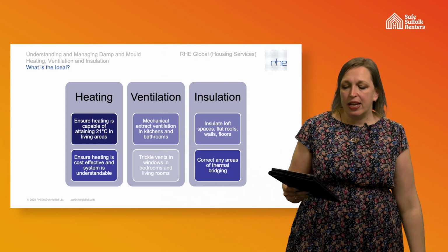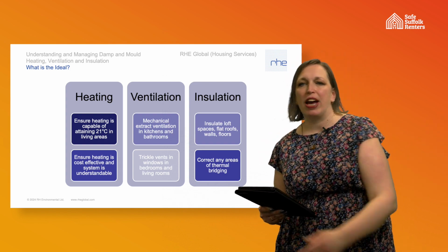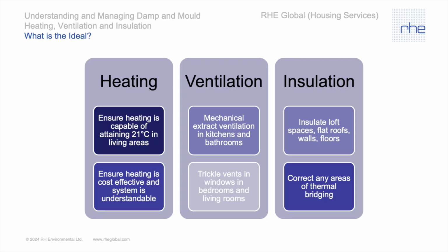And in terms of making it cost effective, that links us directly to insulation. So a tenant can be pumping out the heating, but if we've not provided insulation, it's going straight out of our walls, our roof space. So 35% of our heat is going out through the walls, 25% through the roof. So what do we want? We want 270 millimetres of loft insulation and equivalent in other areas.